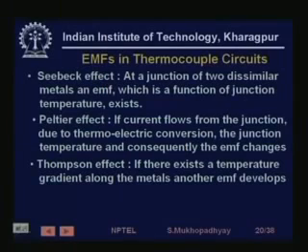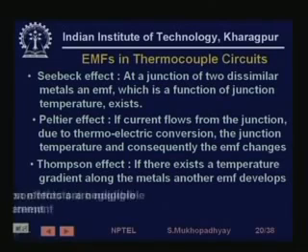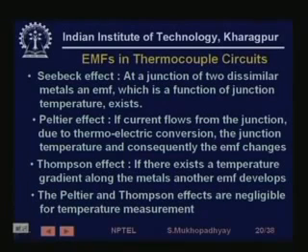So the Peltier effect is generally negligible. Similarly, you have the Thomson effect, which comes into play if there exists a temperature gradient along the metals. Then you have another EMF which develops, but this is also not so important. So therefore, for temperature measurement, the Seebeck effect is the main effect which we are going to look at.